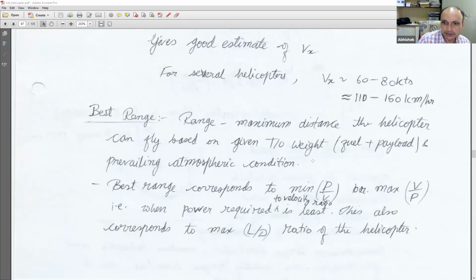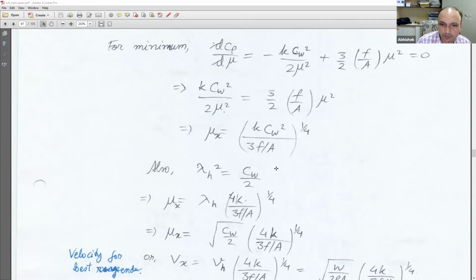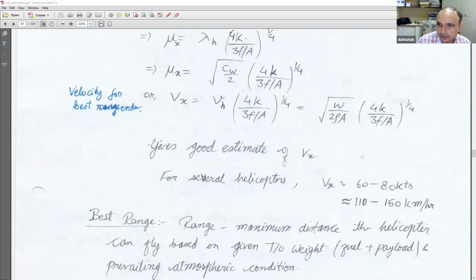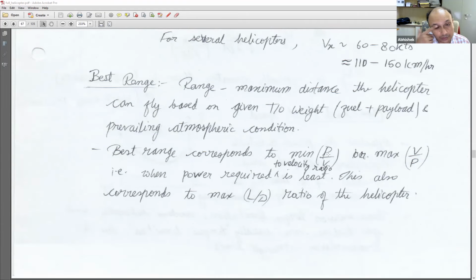Okay, that is the point where my power consumption is minimum for the given velocity, and therefore this P to V ratio. So I want to look at the slope of my power graph at all the points and see where I get minimum slope, and that's why you take the tangent to the line. So we saw that in the power graph that we had.